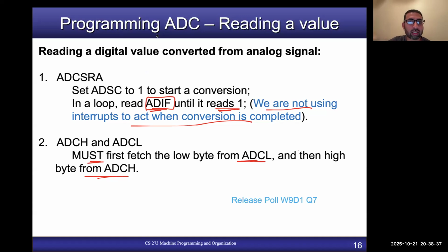Okay, so as most of you have answered, all of you have answered correctly. So you cannot read it in any order. You must first read ADC low and then ADC high.